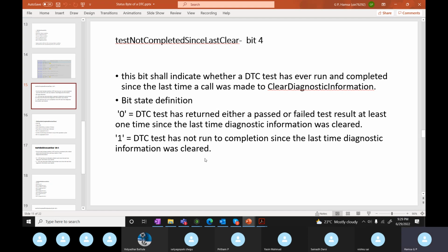This is all about the status of each fault. Okay, but one fault will occur in the DTC. If I do 40 ignition cycles, turn on and turn off, it will automatically be cleared. Yes, nothing but that the fault is not present actively. If it is in history, it will be cleared. If it is active, it will not be cleared, it will be present. Right, now I got the point.